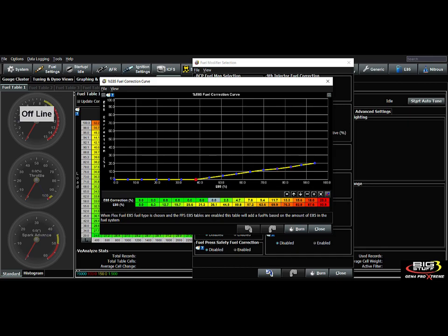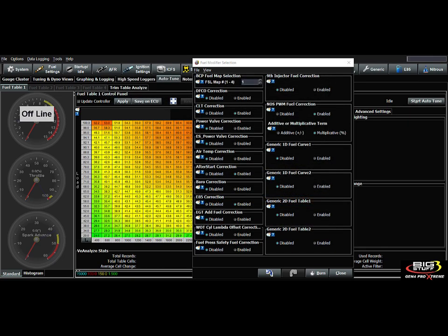It's designed so you don't have to have a ton of adders in there. You may have to. You'll just take some time driving the car around, seeing what it likes depending on the combo. All right, but these only work if you have the E85 option enabled on your computer. Okay. Next one here is we're going to have an EGT add fuel correction.